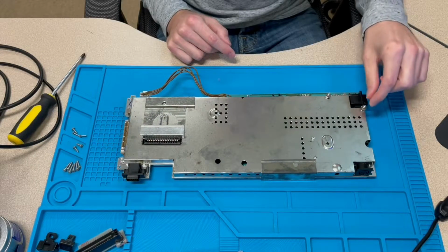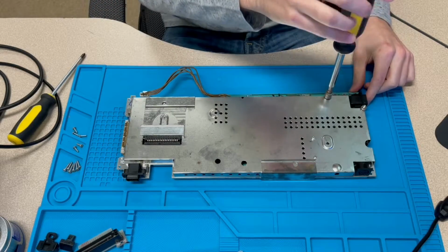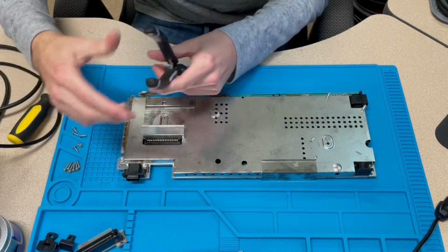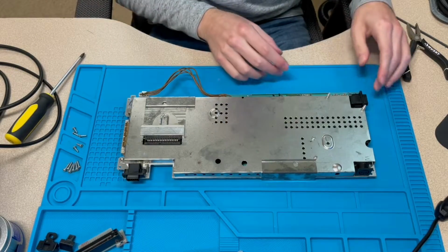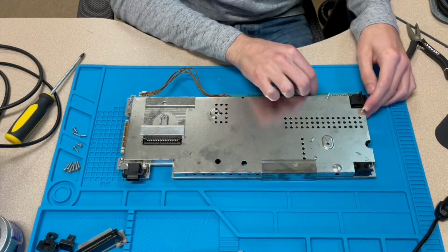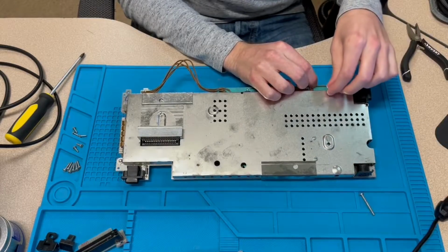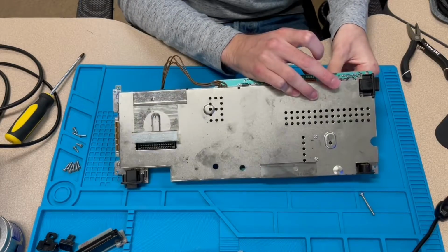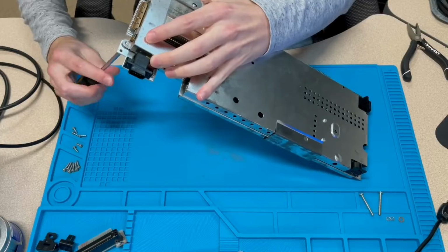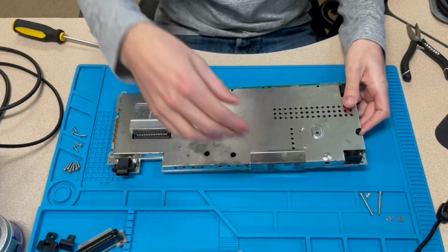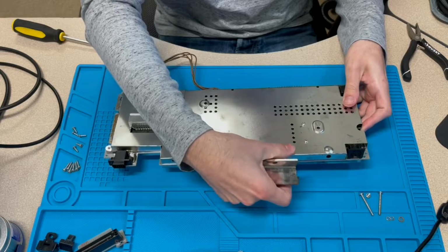And now what we're gonna have to do is remove these 2 nuts and this one. There we go. So now that those nuts are out, I should be able to push the screws out from the back, or at least maybe get them out from the other side. There we go. So there's the screws. You can see they're quite long. So after those are out, now I have to remove these little metal kind of clamping things. They kind of just hold the 2 shields together.